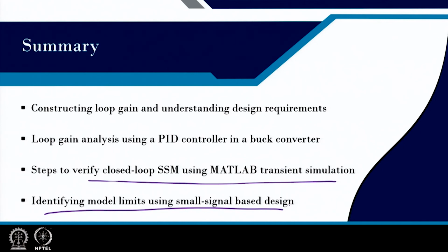In the next lecture, we will talk about the type 3 compensator, where we can go even higher, up to 1/10 of the switching frequency, with reasonably good matching. So, we understood how to match the response of the actual switching converter using the small signal model, and we will discuss the design procedure along with the validation of the model in the subsequent lecture for voltage mode control, for buck and boost, as well as current mode control.